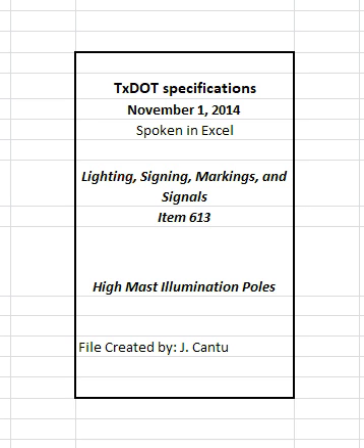Match mark pole shaft sections as shown on the plans. Fabrication plants that produce high mast illumination poles must be approved in accordance with DMS 7380, steel non-bridge member fabrication plant qualification. The Construction Division maintains a list of approved high mast illumination pole fabrication plants.